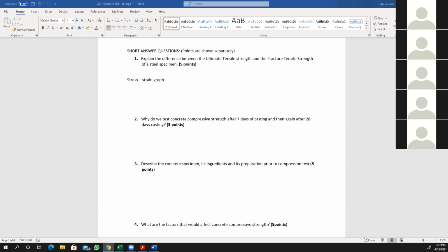Overnight, you see the deformation, rusting on the steel that kills your steel member inside your concrete, and that's caused by shrinkage. So one thing triggers another thing, and at the end of the cycle, you get a weak concrete member, or concrete pavement, concrete column, whatever you name it, due to shrinkage and cracking. So your point was right, that cracks reduce the overall strength of your concrete over time. You might get this strength, 4,500 psi in 28 days. But with time, if you have shrinkage and cracking in your concrete, that number is going to go down over time.